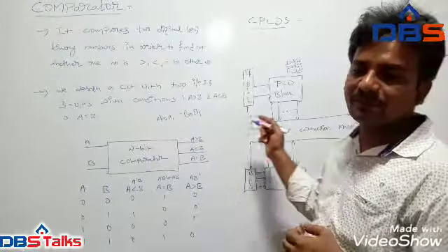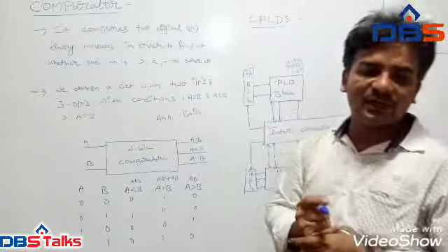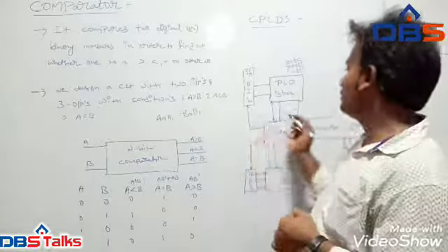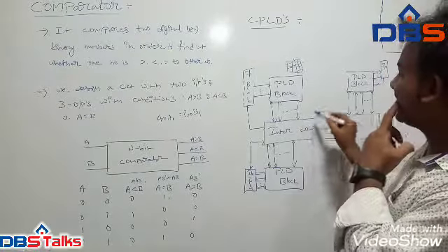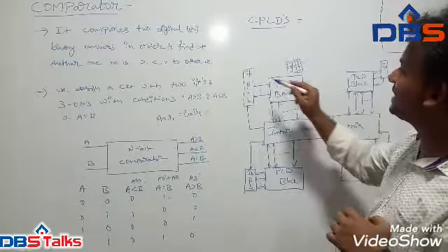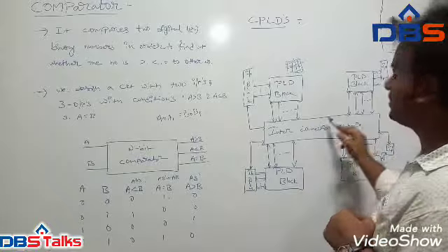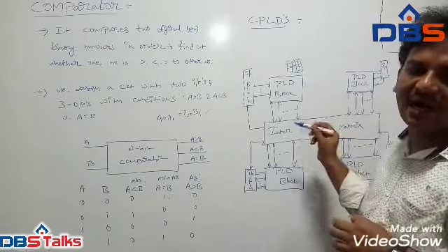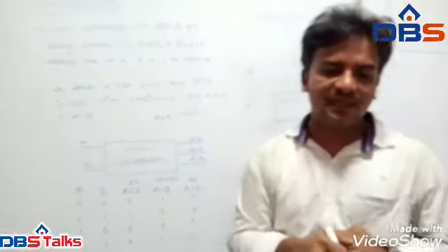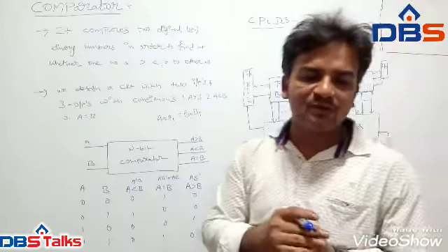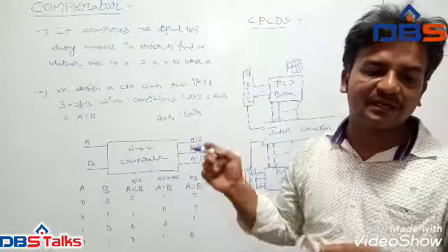So each PLD block is also connected to a subcircuit called the input IO block. So here the PLD is surrounded and controlled by the interconnection matrix and IO block. This interconnection matrix may be designed as either a PLA or PAL. It is attached to a number of input and output pins, so that a pin can be used as the output pin or the input pin.